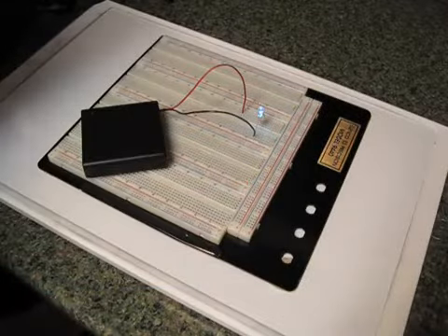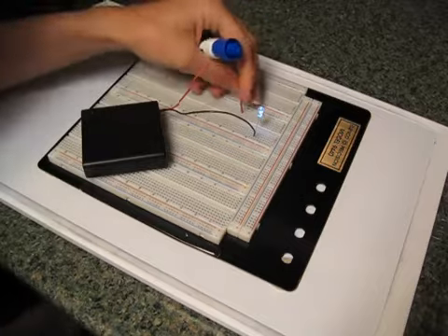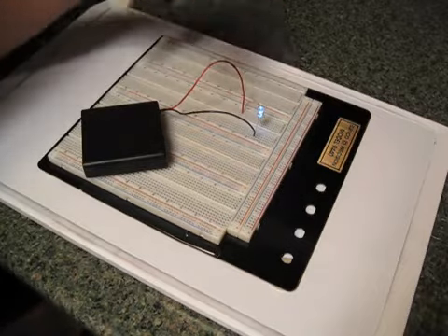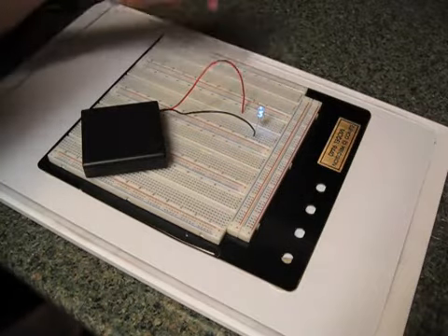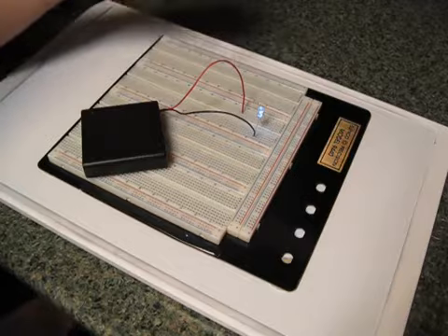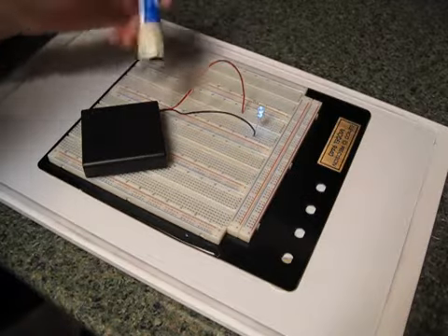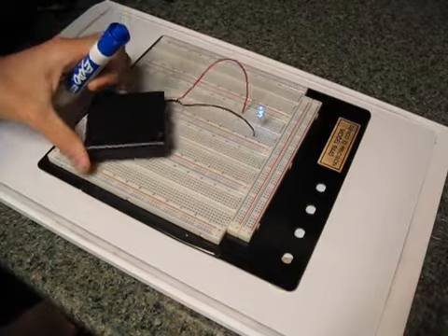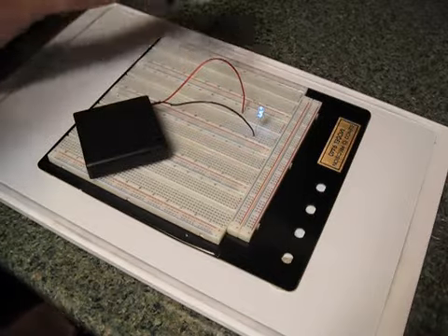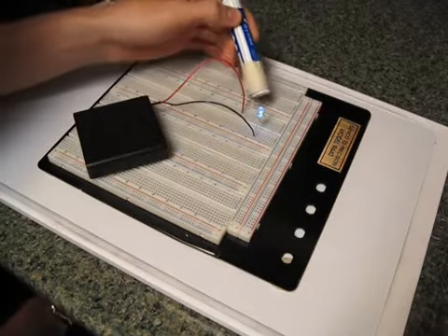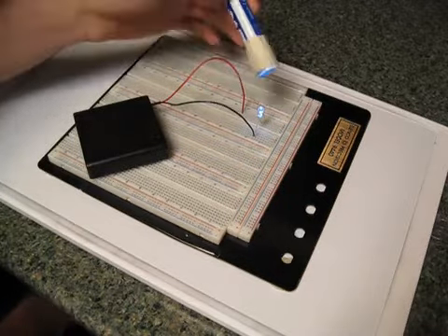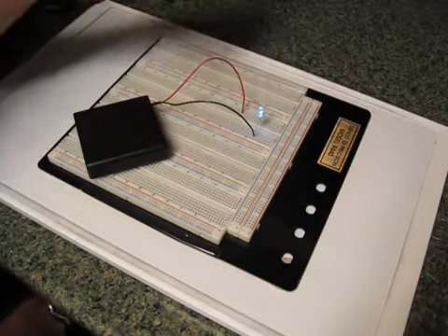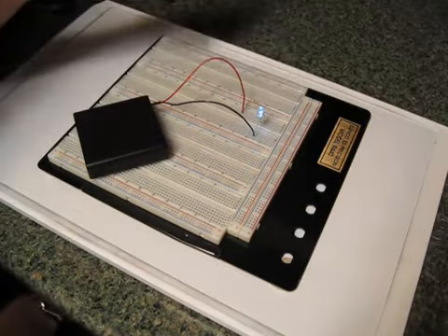Alright, so when you're working with LEDs, you need to use a current limiting resistor so that you don't damage the LED. And most data sheets for LEDs don't tell you what resistance to use because they don't know what your power supply voltage is. So in this video, I'm going to tell you how to calculate this resistance to get the most brightness out of your LED based on the specs of the LED itself.